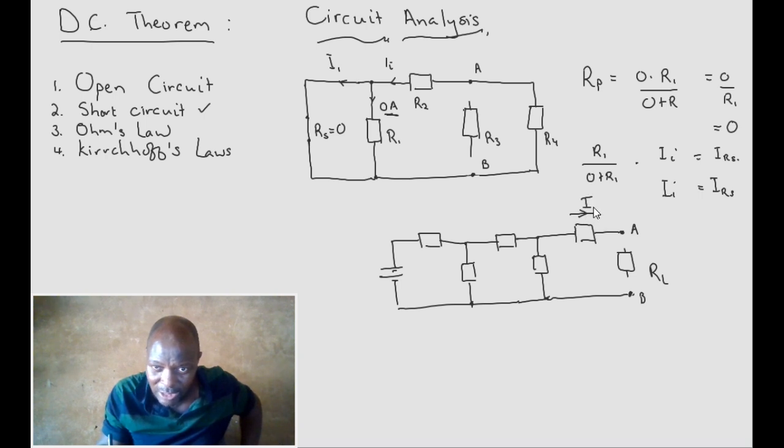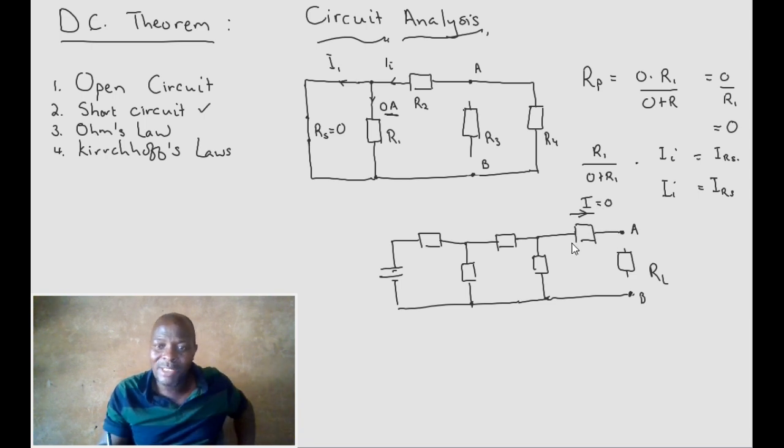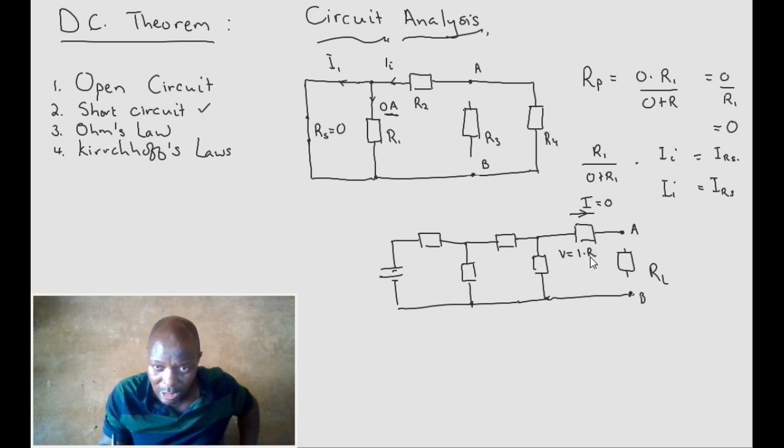So current through this resistor here would be equal to nothing. Yes, it killed the current there. It killed the voltage, because V being equal to IR, according to Ohm, it means there is also no voltage drop here. If the current is 0, then 0 times R, so voltage will also be 0. So there will be no voltage. So the short has the effect to cut out